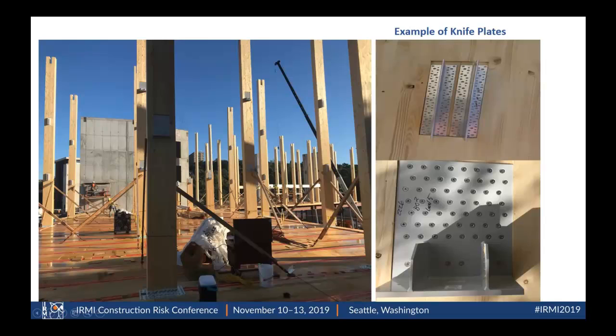So big takeaways from this, and I'll go to the next slide in a second: modeling of the cross-laminated timber for all of your MEPF penetrations, making sure you understand that, making sure they're oversized for UL assemblies. Second thing is making sure you understand your connection details, and that you don't get the wool pulled over your eyes and then all of a sudden it's taken off and you have something with a crazy amount of screws. Making sure that you have water protection measures in place to protect the product, and then looking at your column heights, etc. So those are some big takeaways from this project.